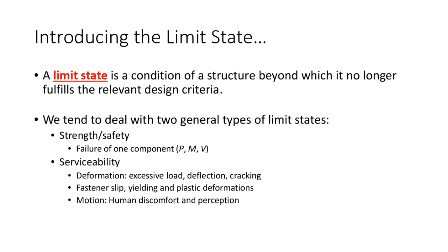Let's take my office. Let's take the floor beams that I'm standing on right now. These floor beams that are holding up this floor are holding up two different types of loads. One are dead loads, being the weight of the beam, the weight of the slab, the weight of the carpet, the mechanical, the electrical, the plumbing, all that, the permanent loads. We call those dead loads. It's also holding up live loads. Live loads are related to occupancy, what the office is being used for. So me, the office furniture, and so forth.